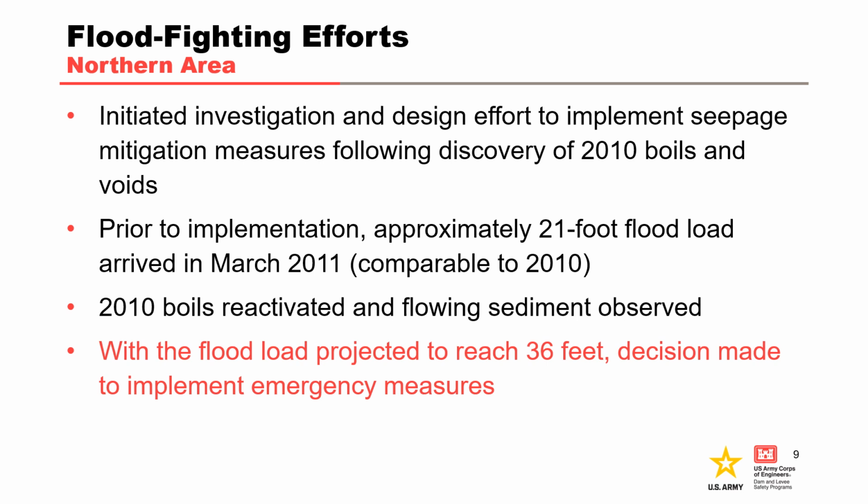Following the discovery of the extensive sand boils and voids in 2010, a fast-tracked geotechnical investigation and design effort for construction of seepage mitigation measures at the levee was initiated. In March 2011, before the permanent measure could be designed and built, the Mississippi rose to 98.95 feet, which resulted in a differential loading of 21 feet, which was comparable to what was experienced in 2010.